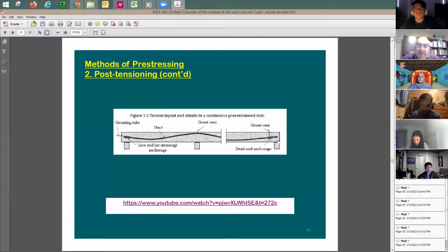But in big bridges, usually you have a grout nozzle. So you have grout input, and you usually inject the grout, because they are also looking for the bond. So theoretically, yeah, this may happen, but practically it doesn't happen. Because how would you get into the slab? Let's say the 20th level, how would you get there and do some tensioning? You cannot. It's going to be very expensive. It's kind of tough. I don't think so.